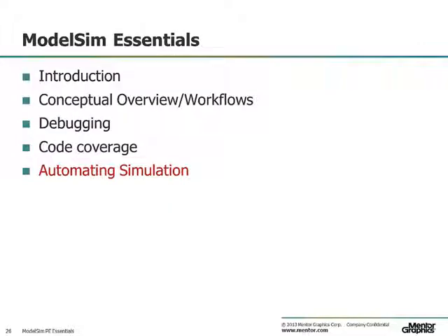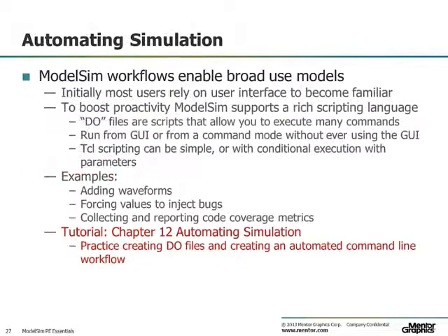So we've covered a lot of ground in terms of ModelSim essentials, and I hope you have taken time to review the interesting parts of the tutorial so that you can gain the valuable practice that's needed to become very productive. So if you've done that, the next thing that you'll eventually want to do is start automating your workflow. Aside from exercising a couple of the pre-existing do files in the previous lesson, ModelSim has a very interactive mode, executing single commands one after the other via the GUI, the menus, or the main window command line. In situations where you have repetitive tasks to complete, you can increase your productivity with do files.